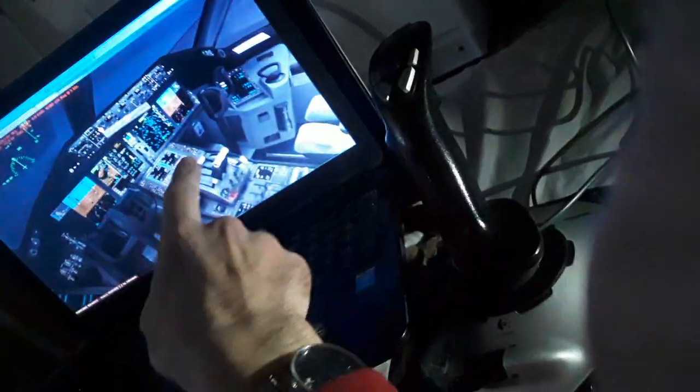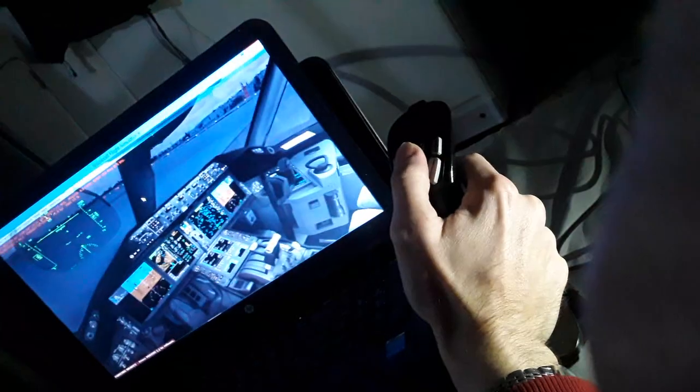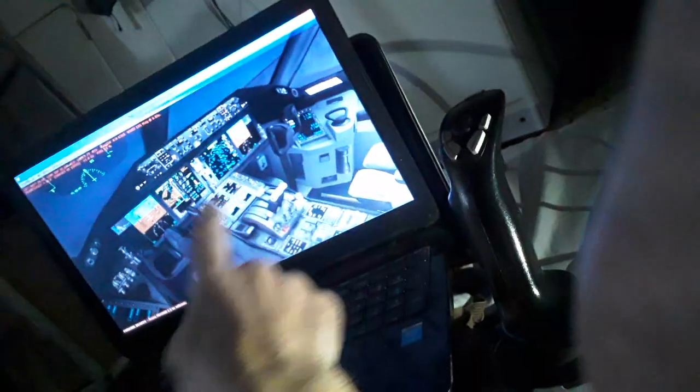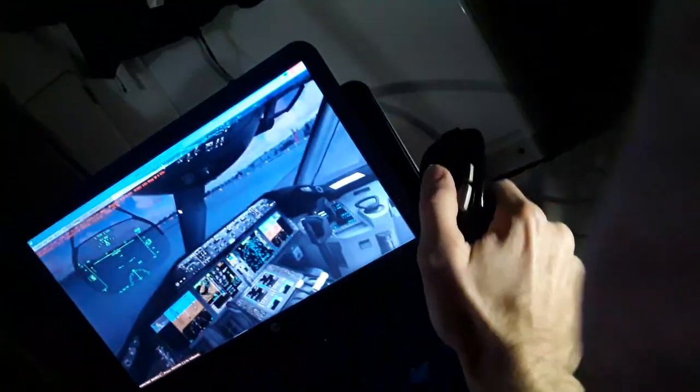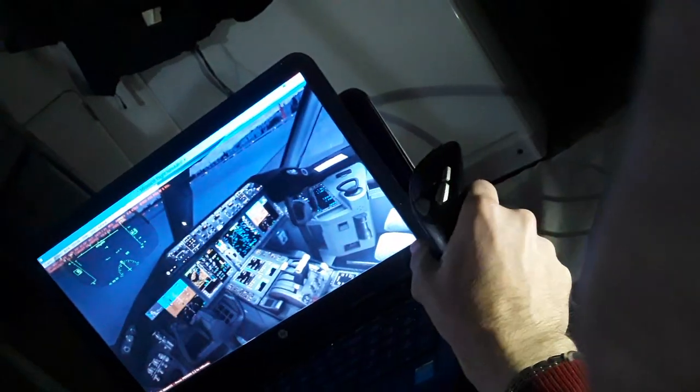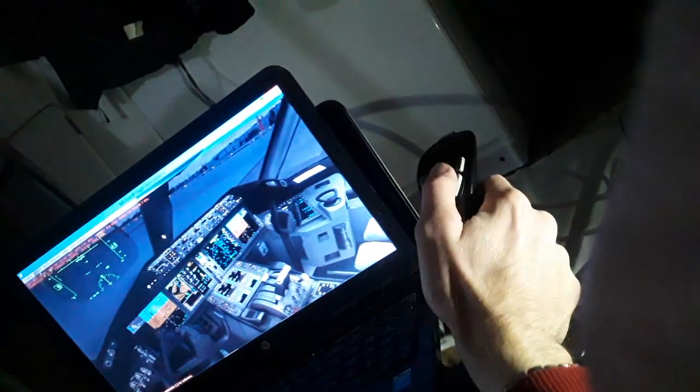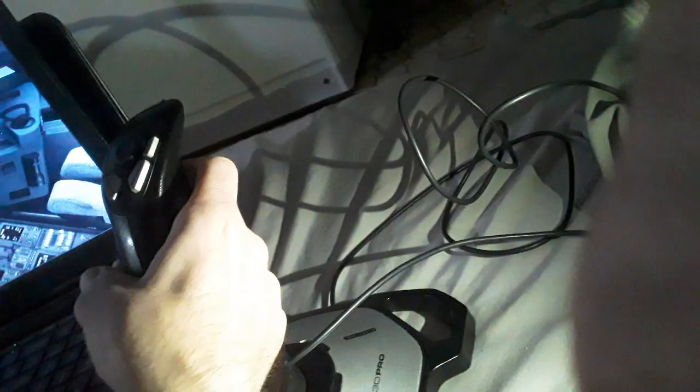So the side stick deflection is proportional to the yoke deflection. Both sides in the Boeing aircraft are interconnected, of the flight controls of the yoke and the control wheel system. You need to use an override force in the Boeing airplane. In the Airbus you have the side stick priority or dual input, also the autopilot is engaged, the push to talk also over here in front. So I hope you like the Airbus and the Boeing flight control system. So very easy to use.